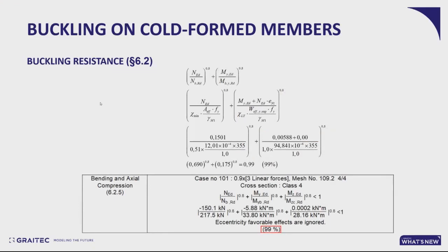And from there, you can perform the actual buckling verification involving the buckling effects from the axial force and the lateral torsional buckling effects on the moment. But here, remember, they were neglected, so we've got a kappa LT of 1. But for the buckling, we are considering the minimum value of the 4 kappa that we had.